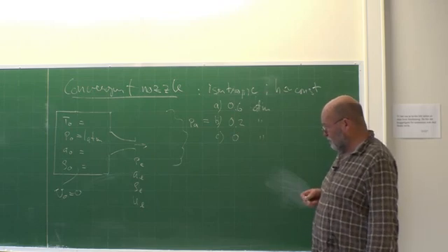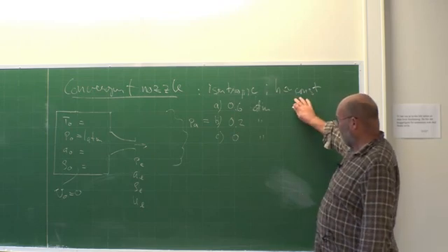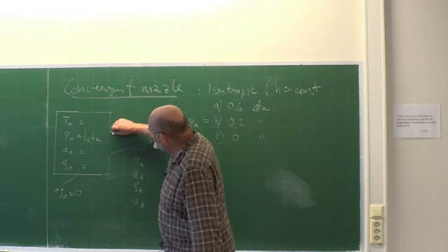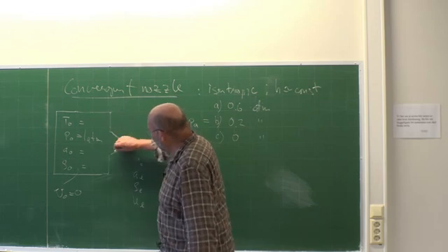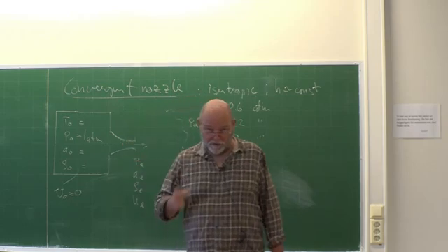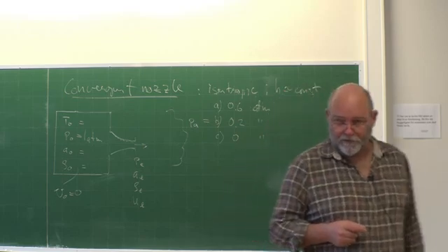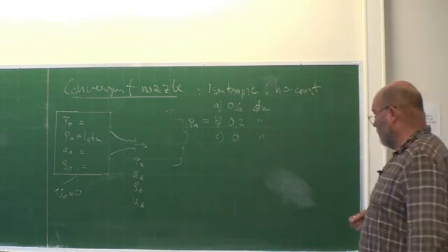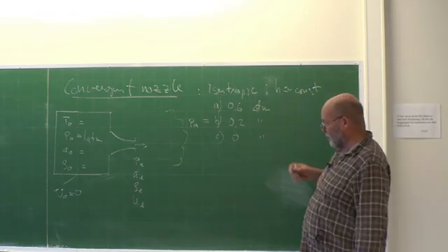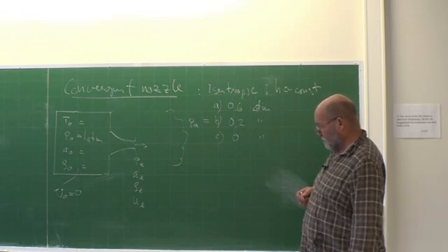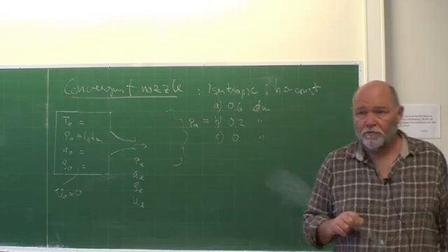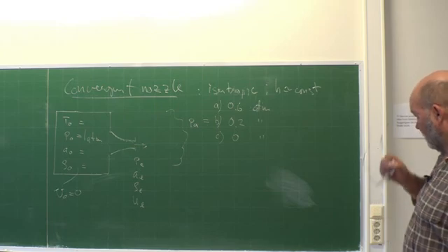So we don't lose energy here. This is okay, except, of course, close to the walls here. Here we have some question marks, of course, sort of in a thin boundary layer there. It's not so good. Not to mention, if we experience shock waves, then this is not correct anymore. But here is more the question, can we achieve a shock? Will we get a shock here or not?